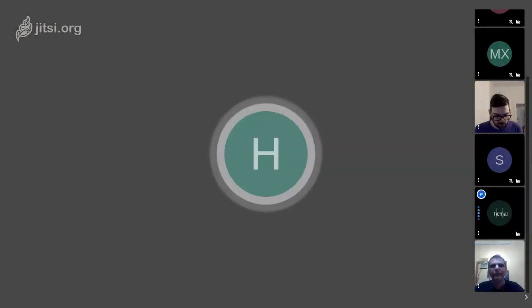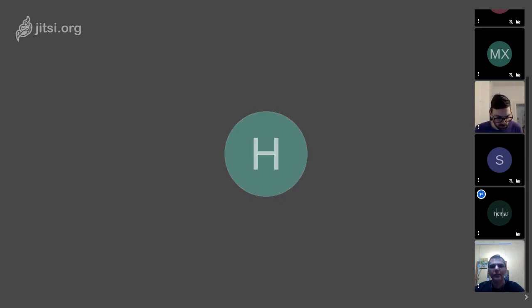You want to share a screen, Drew? Yeah, maybe try importing it instead of opening it. Oh, you need to use the import icon within the StepUp bench, not the FreeCAD file. Oh, right. You have to use the icon with the cylinder.